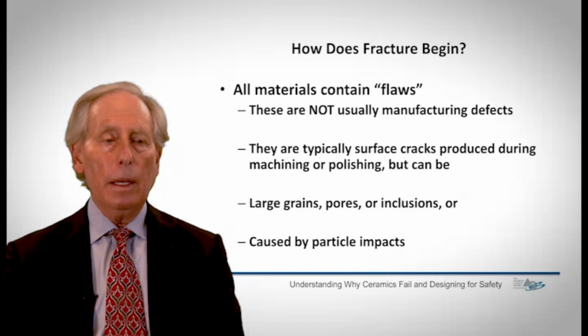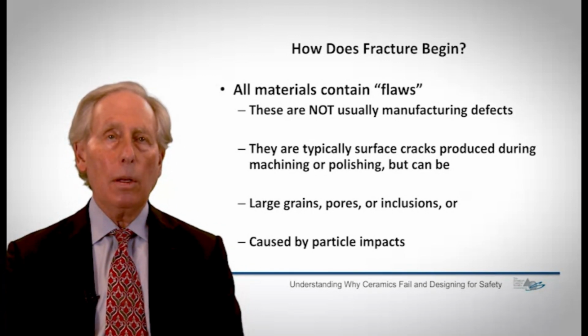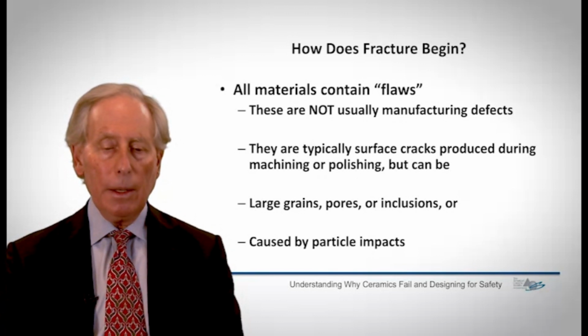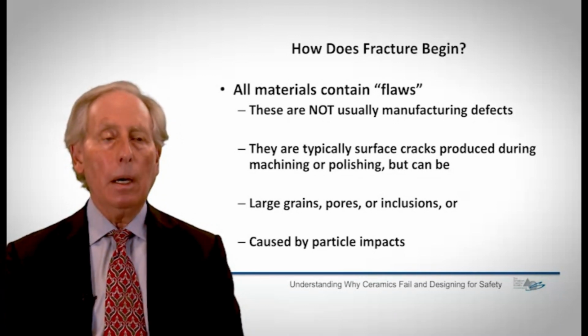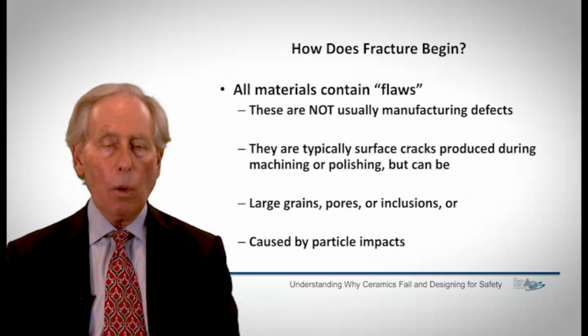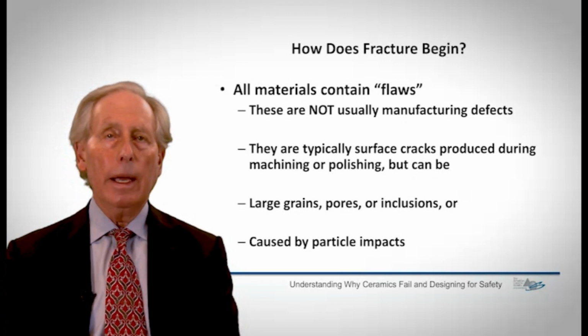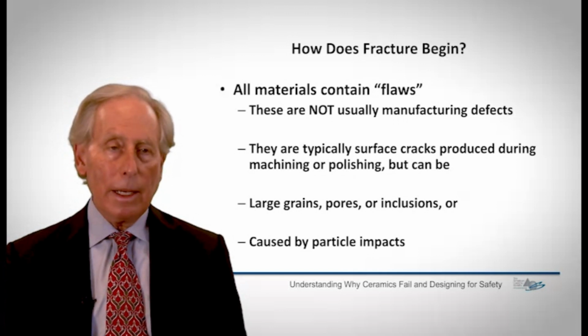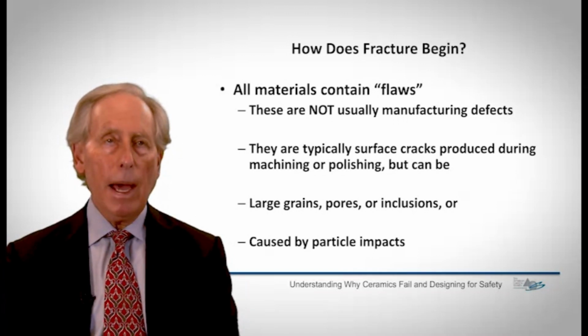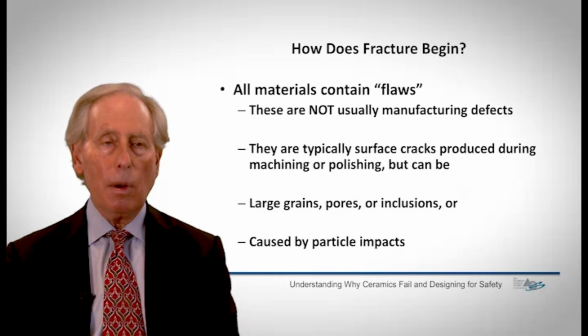And while it is possible to avoid these or make them infinitesimally small, such as in glass fibers, typically these are what we're looking for in most failures. But there can be failures from unwanted large grains, pores or inclusions, incomplete sintering, things of this sort, or, as I continue to say, if there's an impact on the particular component during use, this can be the source of failure because the impact produces these small surface cracks.